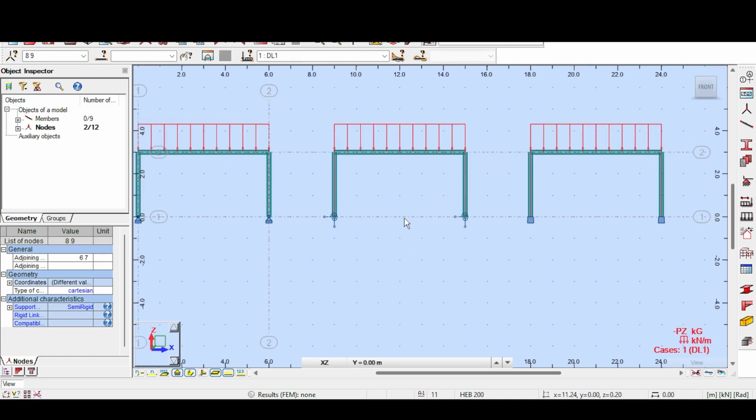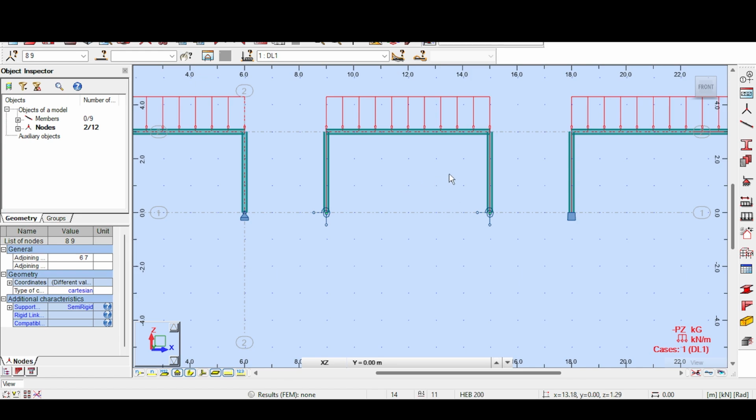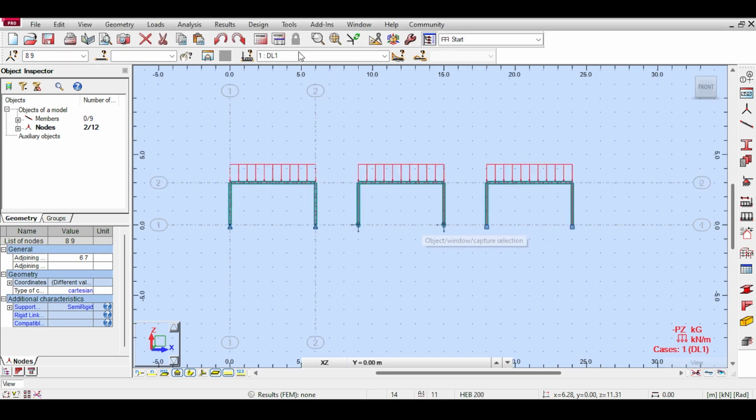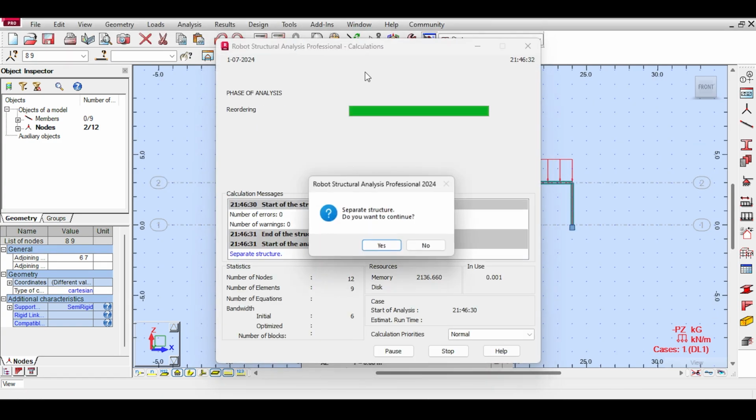Now this time I don't want to design semi-rigid because I'm going to make sure that my base plate is going to be fixed by adding stiffeners and so on. However, I wanted just to add this for the fun fact and so that you can see how the process would look like. Anyway, I will design it, but I'm not going to do the iterative process for that one. So I run the analysis and make sure everything is fine. So let's take a look.